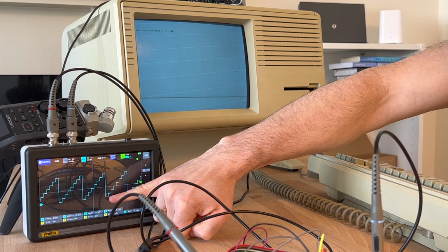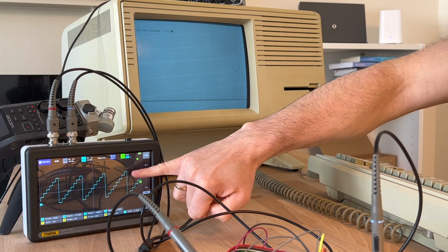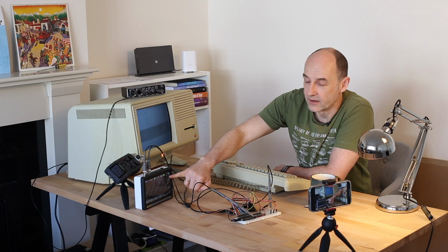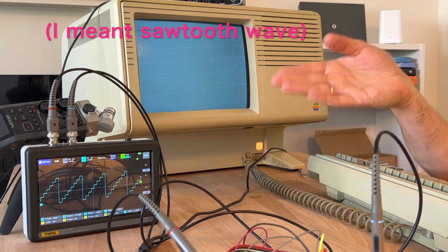So it goes from 0 here, like building a nice staircase in our oscilloscope view, all the way to 111, after which it drops again to 0. We see even from here that we can build a nice wave. This is basically a very rough triangle wave out of 3 bits.